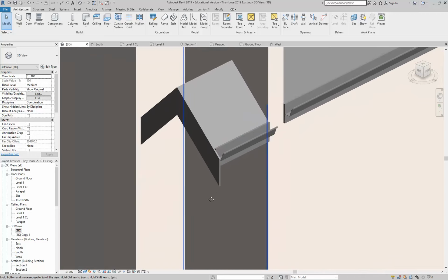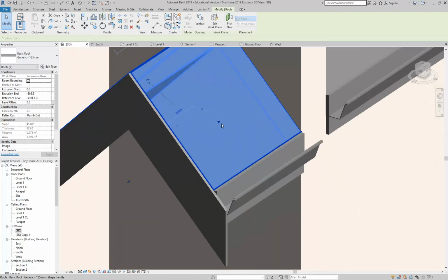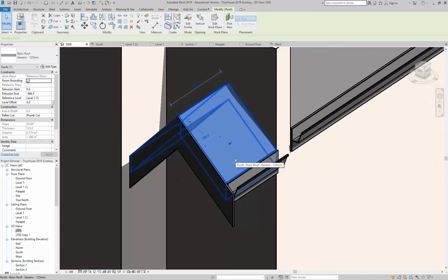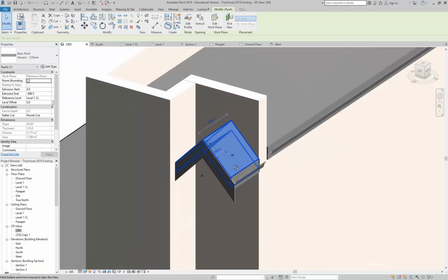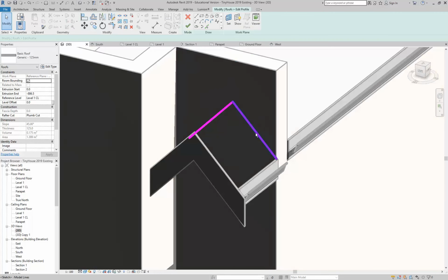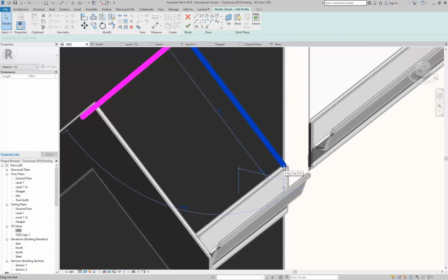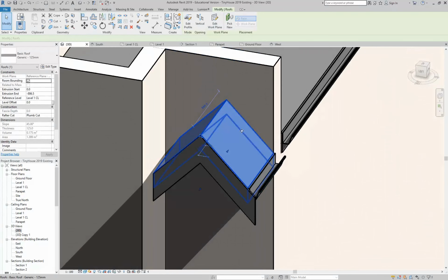So yeah, it's good to just quickly look at this. Again, this is optional. You don't need to put this much detail in, but if you want to have a go at it, you could then leave that gutter on the right maybe, because traditionally they let water run off onto the property, which now isn't such a good idea because of lots of bureaucratic reasons mostly, but Sydney Water essentially don't want you to have that. So I'll leave the gutter there, and then I'm simply going to go back to Edit Profile and